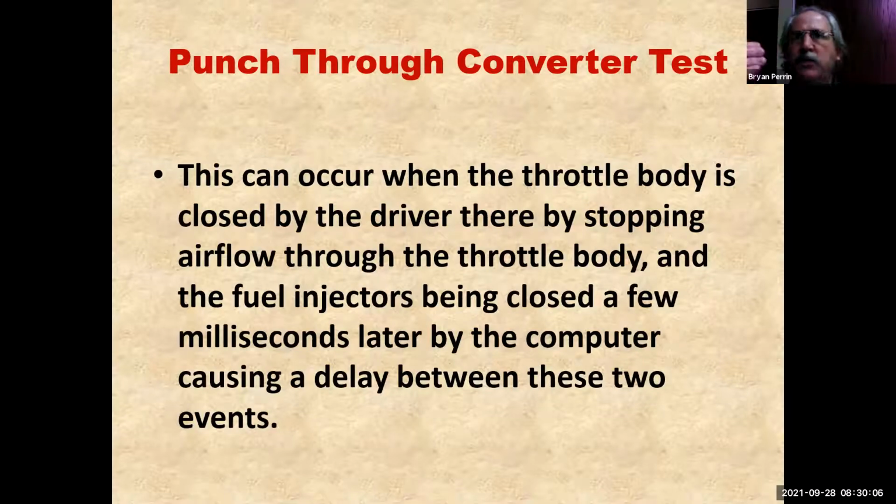Because, again, understanding that there has to be a delay. If I'm looking at a sensor on a throttle shaft, and I close the throttle shaft, I've just shut off air. It takes time for that signal to get to the computer, and the computer to go, oh, shoot, we need to turn off the injector. So there's going to be a few milliseconds there, a few engine revolutions, because my engine is going at 2,000, 3,000 RPM, which means I'm firing those injectors very quickly.